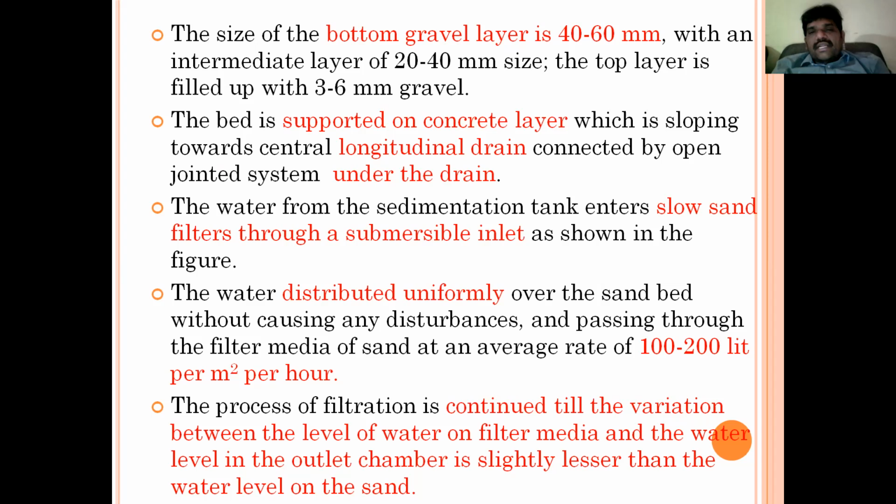The bed is supported on a concrete layer, which slopes towards the center. Just remember the settling zone structure in sedimentation. As the water enters the central part due to the sloping bottom, from there the water will be sent out. See here, next the water from the sedimentation tanks enters slow sand filters through a submersible inlet as shown in the figure.